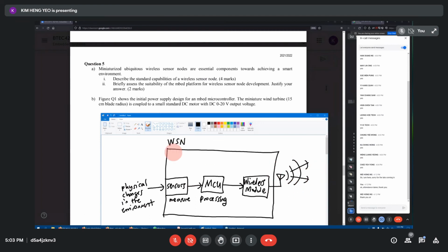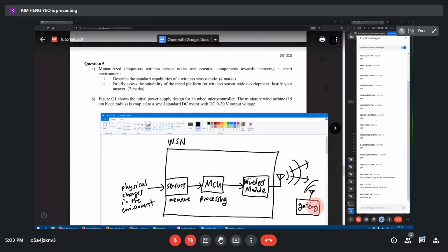So you are setting up this wireless sensor network, let's say in your factory. In your factory, you will have a gateway. The gateway is the device that connects to the internet. The gateway is normally a computer. This computer will collect all the information from the sensors, right? And then send them through the internet. It's better than putting internet capability on a small low power sensor like this. For a small low power sensor, it is better to put a simple wireless module like Bluetooth Low Energy or a simple RF transmitter receiver, rather than fully Ethernet capable.